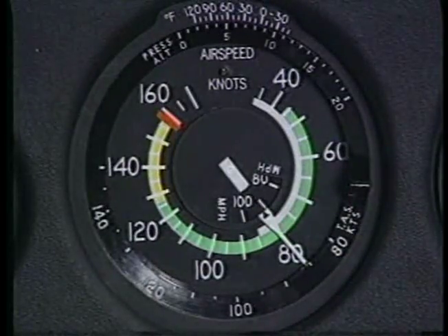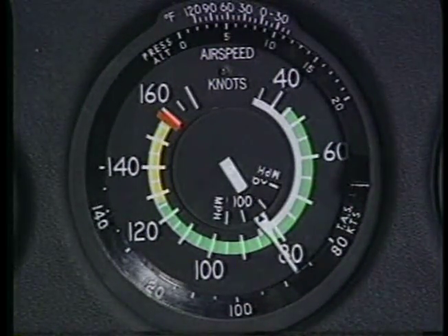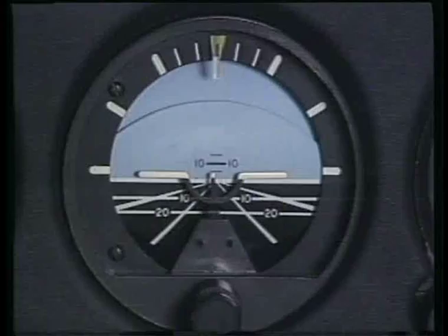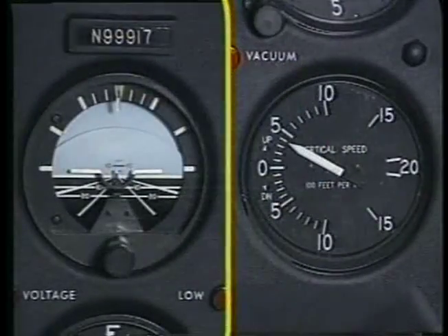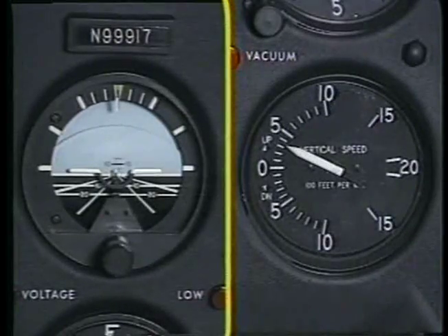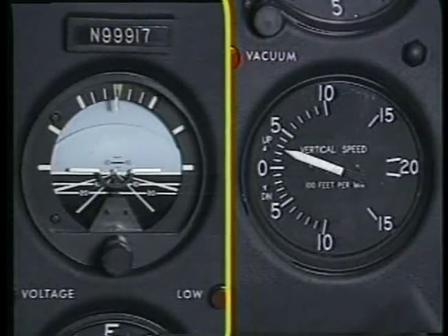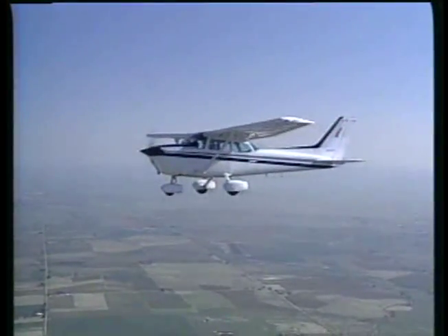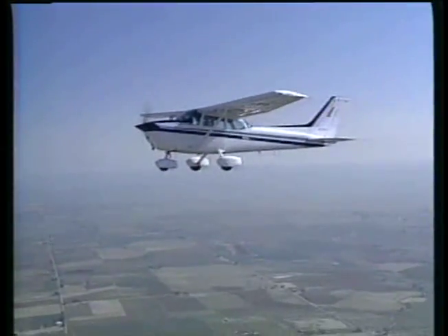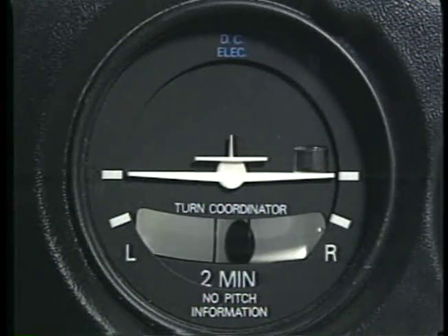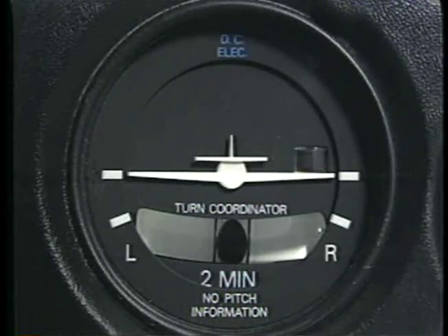During a stabilized climb, any change in airspeed signifies that the pitch attitude has changed. To correct the pitch, use the attitude indicator. Your actual rate of climb depends on the density altitude, power setting, and aircraft weight. But the VSI can provide an indirect indication of pitch changes when it increases or decreases. In a climb, you maintain directional control the same as in straight and level flight, with one exception. The ball in the turn coordinator is scanned to ensure that you are applying enough right rudder pressure.